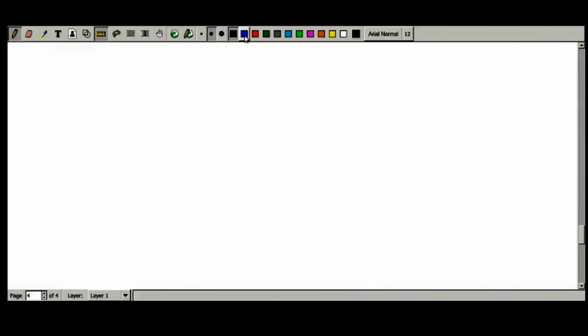And what are the things given to us? We are given the following: terminal voltage Vt per phase, armature terminal voltage, load power factor angle theta, armature current Ia per phase, armature leakage reactance XL, and armature resistance per phase, that is Ra. These are the things provided to us. Based on this we have to draw the phasor diagram. So we will start with the terminal voltage Vt.